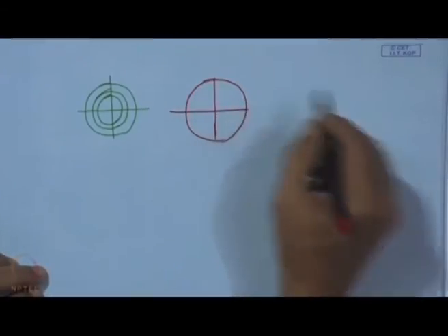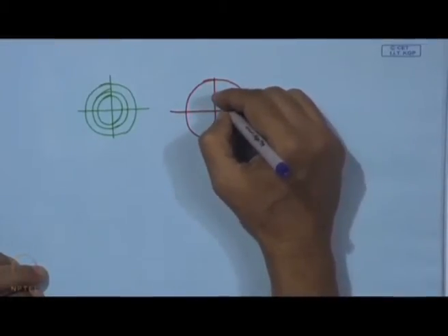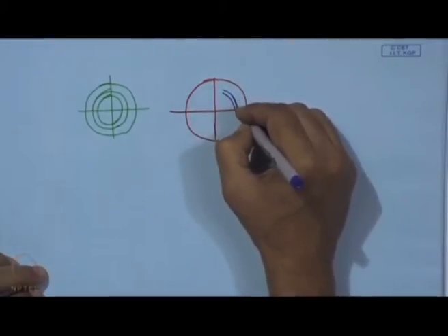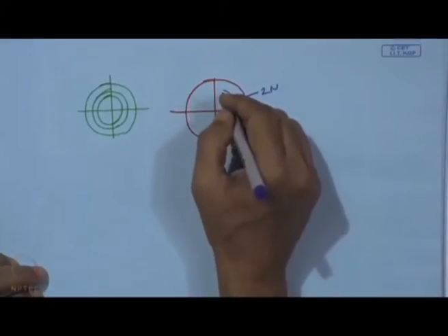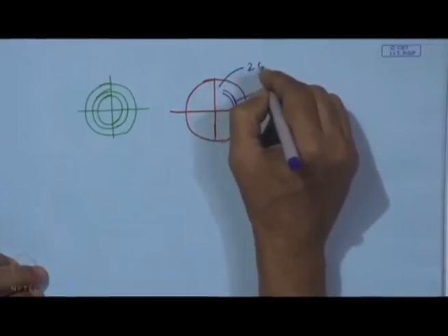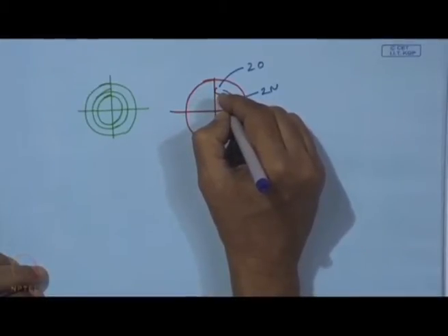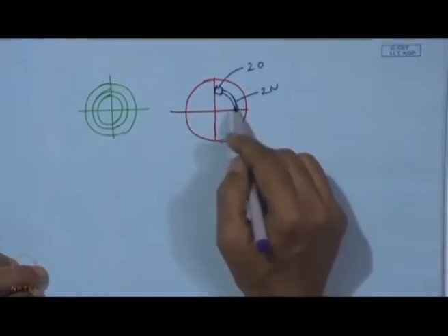the disc, but here reciprocation is restricted only to 90 degree, and what would be interesting, up to 80 degree we have a wear track of this width, because the load is now 2 Newton, and then from 80 to 90 within this 10 degree, because now the load is 20 Newton, the shape of this wear track will be a little bit enlarged. So, we expect this enlargement of this wear track over this, and that will be recorded,